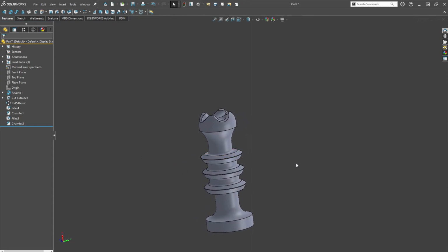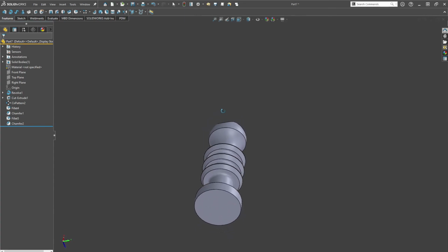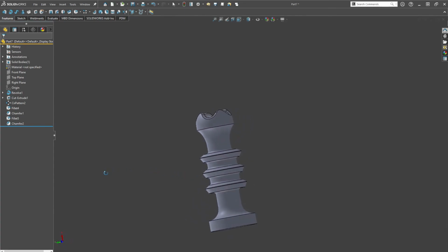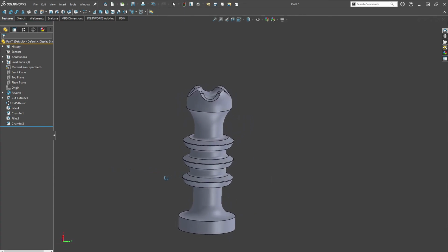Anyway, this is just an example of how you can do circular revolve shapes. Again, you can use something like this for shafts or chess pieces, bolts, if you need to model something like that, anything cylindrical. And this also works for when you have something cylindrical that protrudes off of something that's not round. Like let's say that you have a trophy.